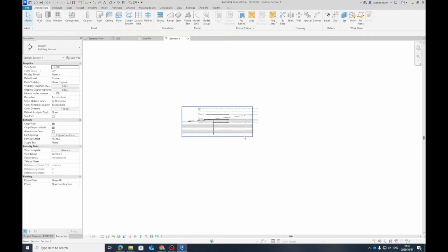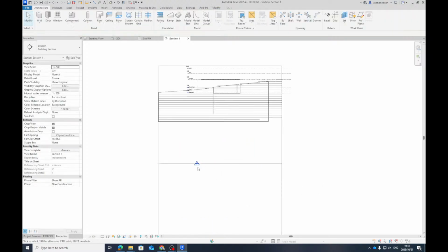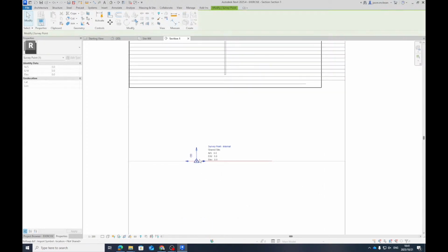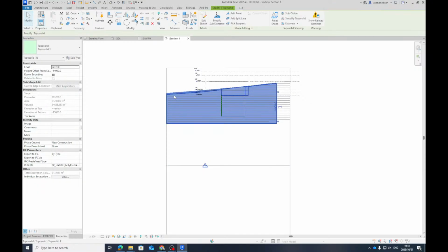So what I'm going to do is create a new level. This is my C level. I'm going to tell the top of solid to associate to my C level rather than level 0. Then I can get rid of level 0. Another trick we can do: I'm going to copy this value.